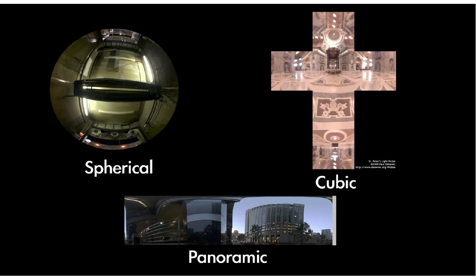You can also use HDRI lights. It's actually called an environment light. It uses an HDRI image, which stands for high dynamic range image. It's a pixel image that has not only the color data but also the light intensity values of that image when it was recorded. Now you can see that this image will automatically be mapped around your scene in either a spherical, cubic, or panoramic way, and it'll project light into the scene from that image. So it actually has the light information recorded in that image. It's pretty cool. And if you search the internet, there are a bunch of free HDRI images that can be used.